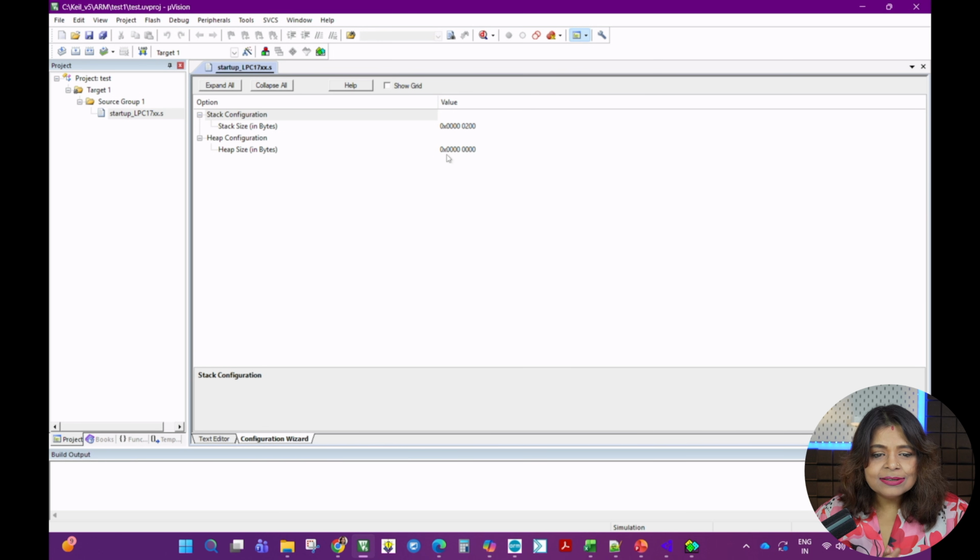So you have defined some memory for stack, and some RAM is used to store your variables, some data, information and everything. So in your application, if you need runtime memory during the application execution, if the processor needs a few bytes of memory for some data storing or processing, it can use heap. It can take the memory from heap. So if you are planning to use any such dynamic memory allocation routines in your program, then please define this heap.